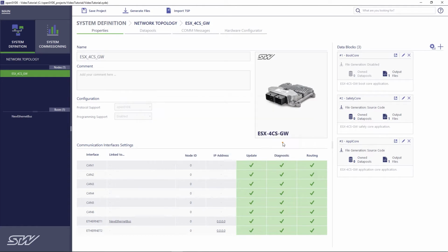The application on the boot core has mainly the task to start the controller with the applications on the other cores in an orderly way. This is usually not changed. Therefore, no code generation is enabled for it. When using functional safety, the application on the safety core is used to record the safety code. Here, all the minimum necessary functions are already programmed by the template. You could generate code for this application, but we will not edit the application in this tutorial.